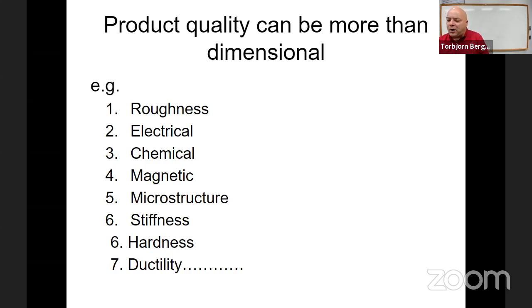You can get a qualitative measure of the roughness of that part, which is good enough to control the manufacturing of things like nuclear-powered submarines. So the thumb scratch method is how they check the surface roughness of weldments on nuclear-powered submarines before they put them in the water.